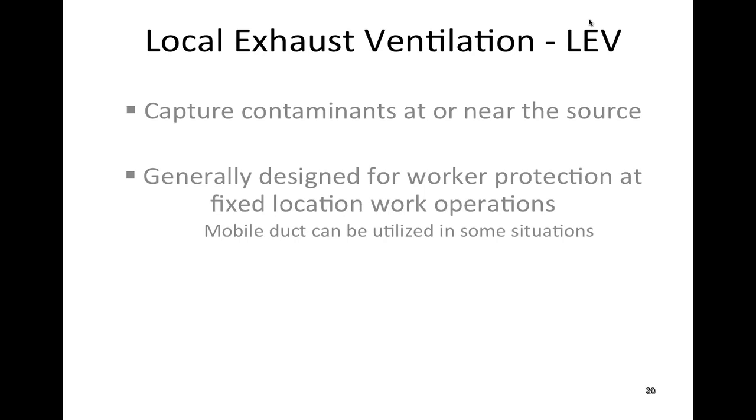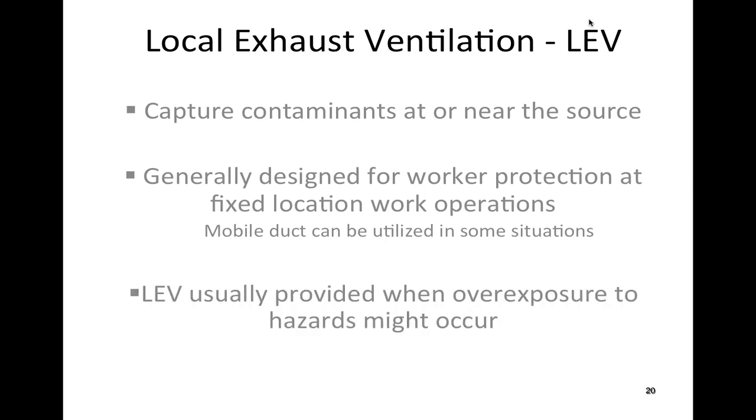So they all impede. If we have a long run of ductwork versus a short run of ductwork, with the geometry otherwise the same, same fan, same diameter, and so on and so forth, we may not be able to move air as efficiently or quickly. We won't have the same velocity if we have that long run of ductwork, because that's a lot of resistance to the movement of the air.